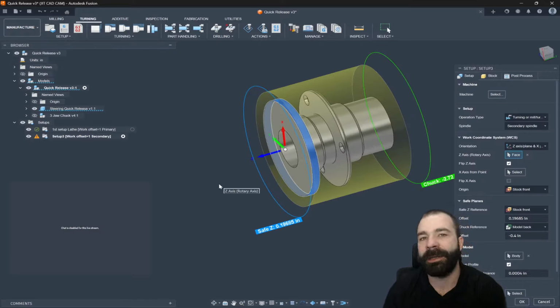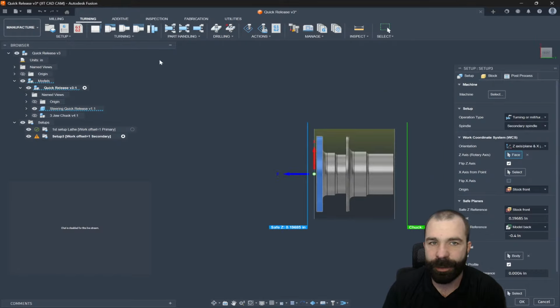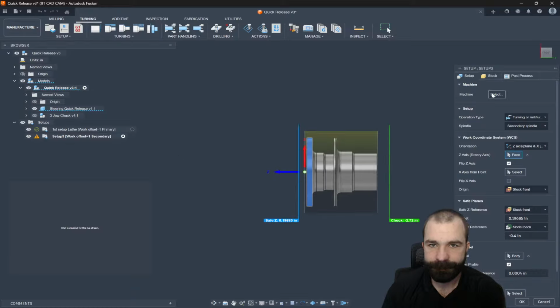That is all handled in the post processor, so you don't have to worry about that. You just have to keep in that mindset where my tools are coming from in Z. So you always want to point at basically the turret on your machine, which, if I looked at this a little bit cleaner for you guys, is my turret would be sitting somewhere over here, meaning my tools come in left to right towards my part. Again, that blue arrow needs to point at the turret. The post processor will handle flipping the coordinates to be either Z positive or Z negative.